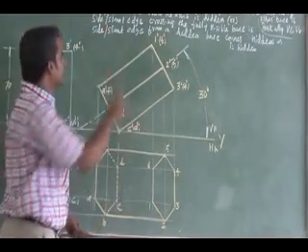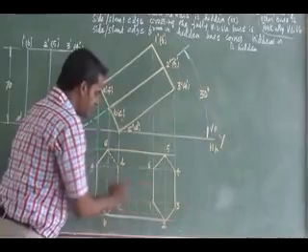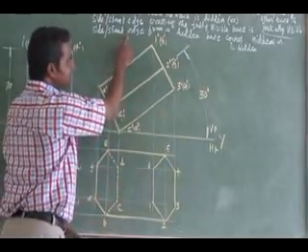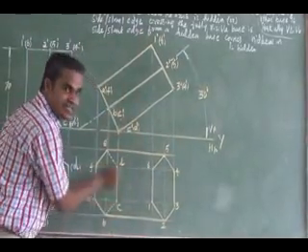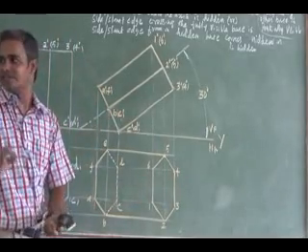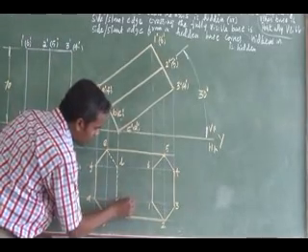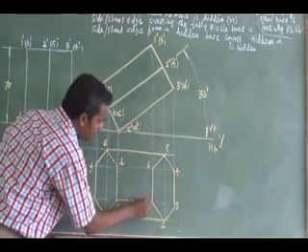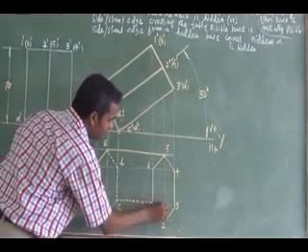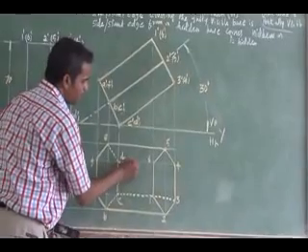As per the second statement, the side edge crossing the fully visible base is again C3 and D4. As per this statement, again the hidden corners are C and D. From that hidden corner, whatever side edge I draw is hidden. So my only hidden side edges are C3 and D4.